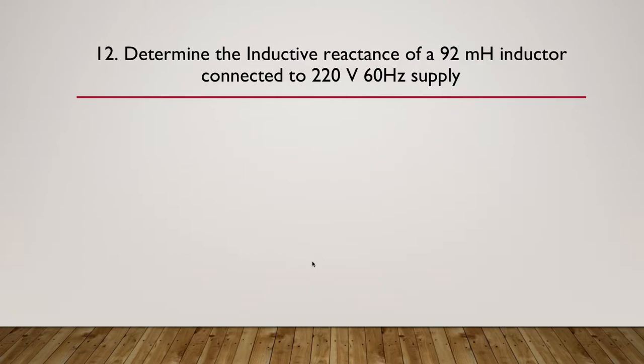Question 12, next question. Determine the inductive reactance of a 92 millihenry inductor connected to a 220 volt 60 hertz supply. So this time, determine the inductive reactance. So time to pause the video here while you select the appropriate formula and do some calculating.